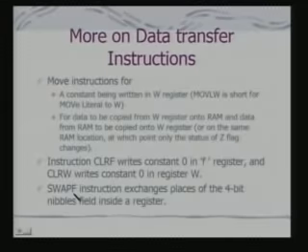The last instruction that we are referring to here is the swap instruction. Now, swap instruction, what does it do? It swaps the nibbles of a register. That means it exchanges, and this exchange takes place in a single instruction. Typically, when we try to exchange the values of 2 memory locations, we require a third, a temporary location.